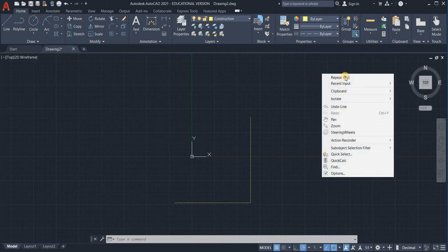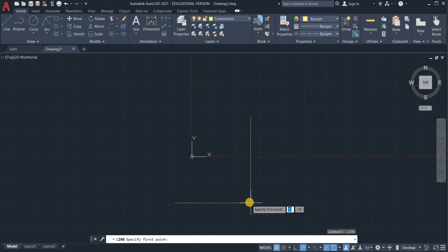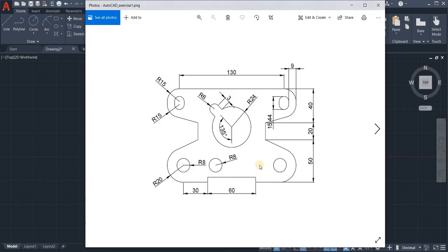Okay, let's go ahead and repeat the line command. Okay, so we're just going to draw a line. I'm going to set that line to equal the 27. Alright, and I'm getting 27 from the radius of the circle is 24 plus 3 for those line segments.